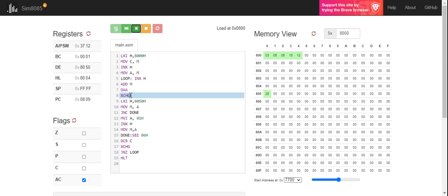So now what am I going to do? Again, exchange this particular value over here. When I exchange this particular value, 8004 is gone back over there. HL is coming over here. Now I'm going to load that particular value. What is my output? 37. 37 is moved to where? My particular output location 8050. And that is my 37 over here. No carry generated. You see that no carry is generated over here.